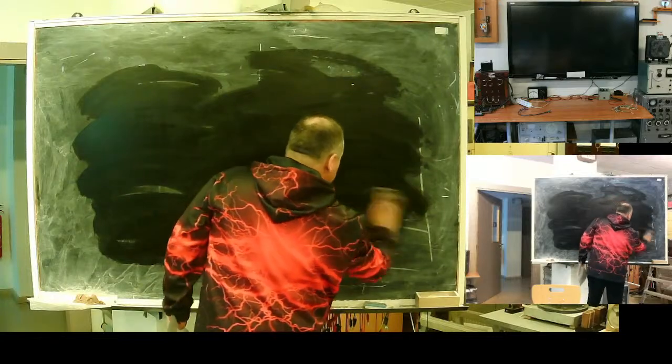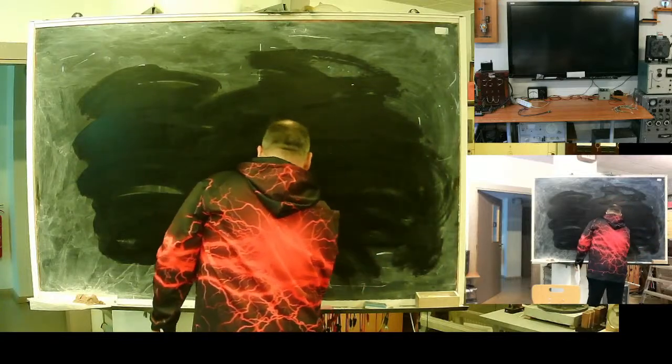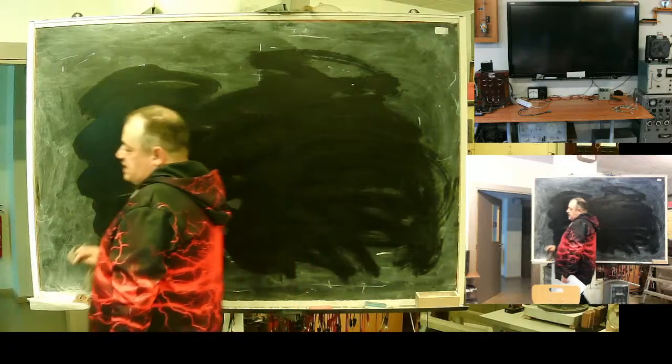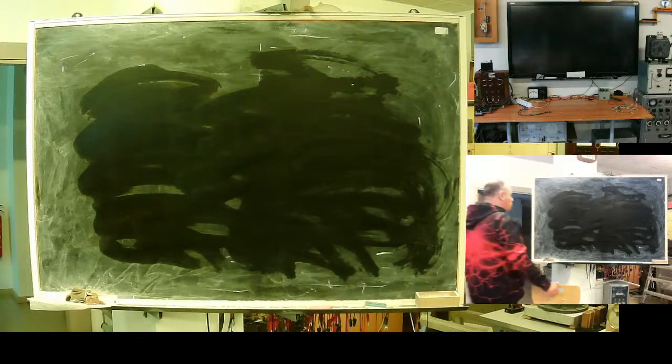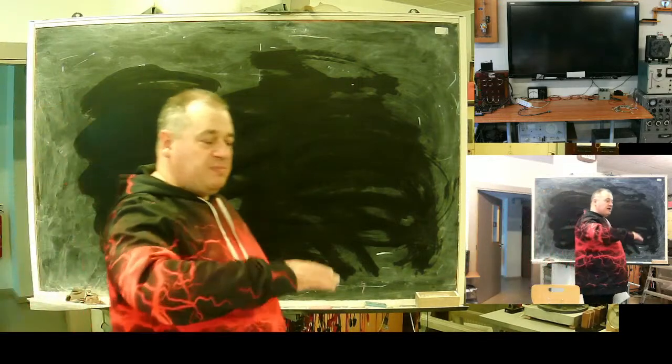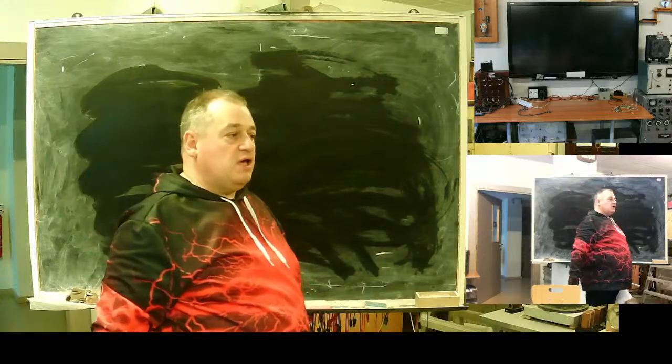It's done with purpose. This type of relays, they are lazy to return. It's done with purpose because overload may not be constant, it may go up, down, up, down, up, down. So these relays are lazy to return.